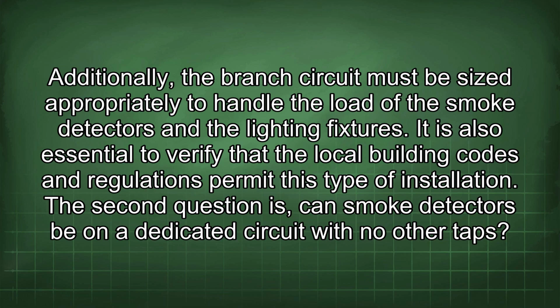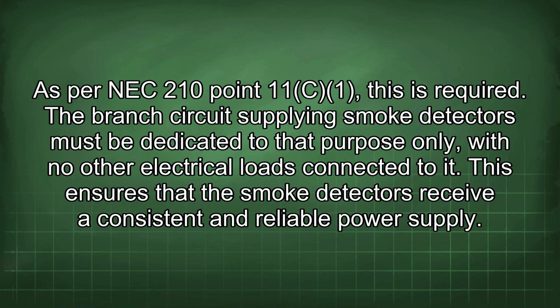The second question is, can smoke detectors be on a dedicated circuit with no other taps? As per NEC 210.11(c), this is required.